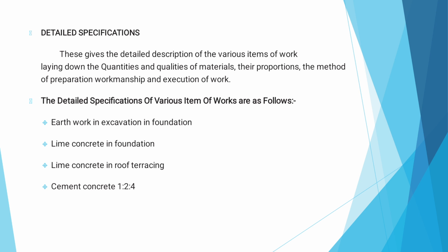The next one is cement concrete 1:2:4. There is also, first one is material. Aggregate shall be an inert material and should be clean, dense, hard, sound, durable, non-absorbent. That is the material character. And then proportion, then how to mix, hand mix and machine mixing, slump, formwork and laying, then curing, then finally measurement. That is the same concept.